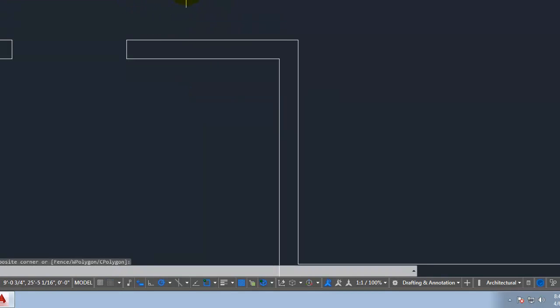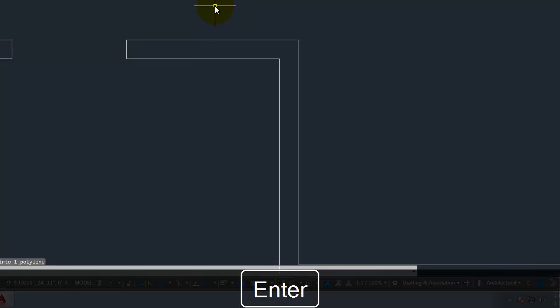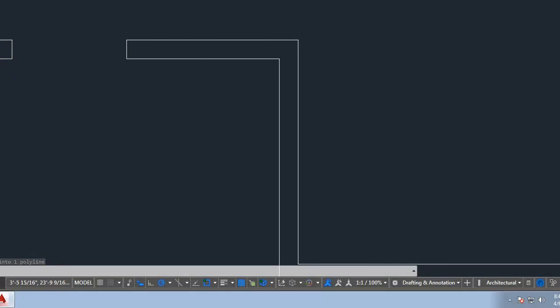So I'm going to go from the right to the left, selecting all the objects, and then I'm going to join them together. And I think it's under here. I always just type join, but I'm kind of curious if I can find it. Yeah, I don't know where it is. Just type join. And these will join together into one continuous object. Okay? So I have those drawn now.